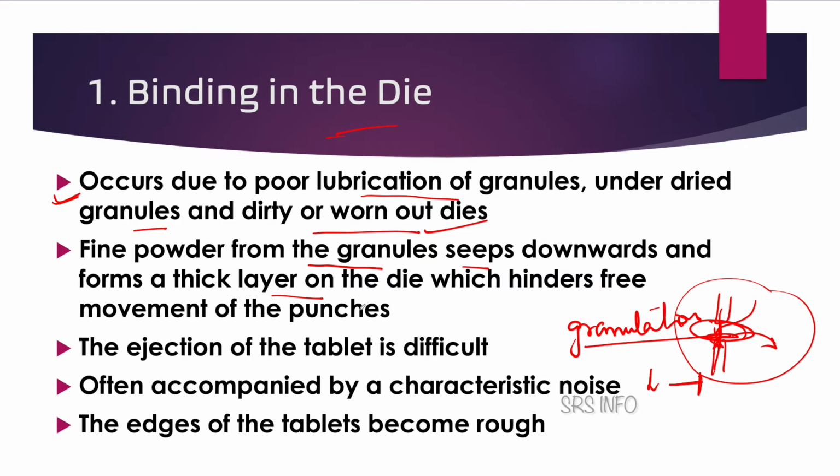So if the powder is extremely fine, then the fine powder from the granules seeps downward and forms a thick layer on the die here, which hinders the free movement of the punches. If the powder is extremely dense in this area, then the punches cannot push up and come down. This will lead to binding in the die. The ejection of the tablet is very difficult if the granules are not properly pressurized to form the tablet. If binding in the die occurs, then it is very difficult to eject the tablet.